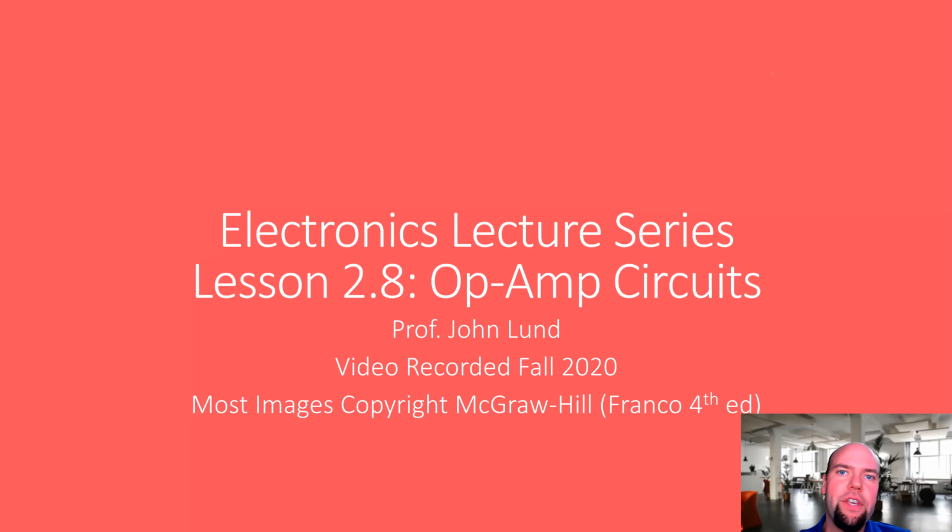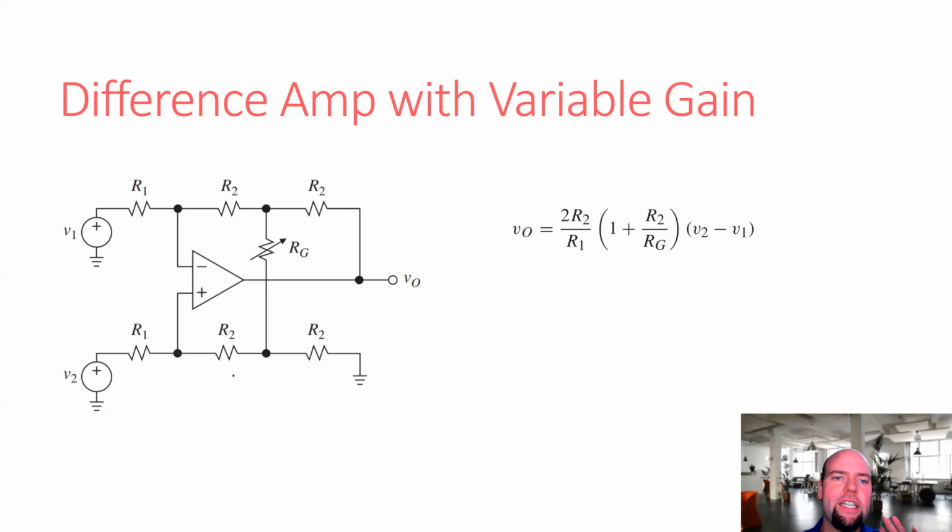If you've got a strong signal, a voltage signal with a low impedance, or a current signal with a high impedance, you don't necessarily have to go with the circuit that we're going to talk about at the end of the lecture today. But if you don't have control over that, that's when you want the circuit we're going to talk about. To get started, let's go back to our old friend, the normal difference amplifier.